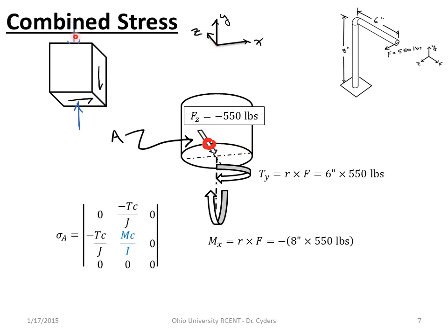At point A, we have this stress cube effectively aligned to these axes. And so we have a compressive stress in Y because of bending. So that's our axial stress here along the y-axis. And then we have a shear stress along the y-x axis. So remember that at point A we said that that's aligned to the z-axis, and because this point on the z-axis is radial here, the two planes involved in shear are then going to be x, y.